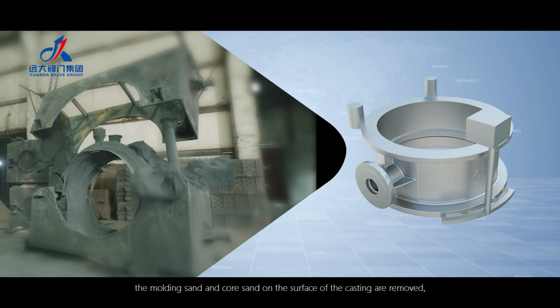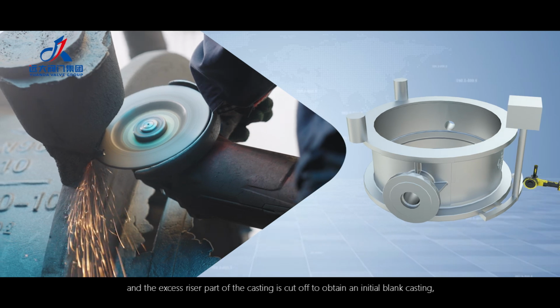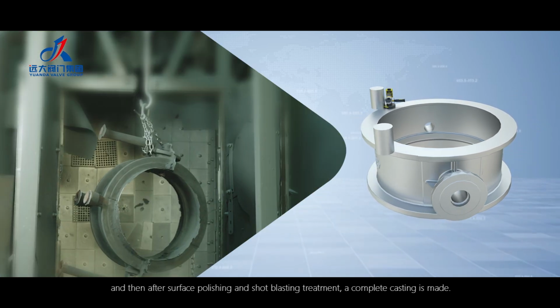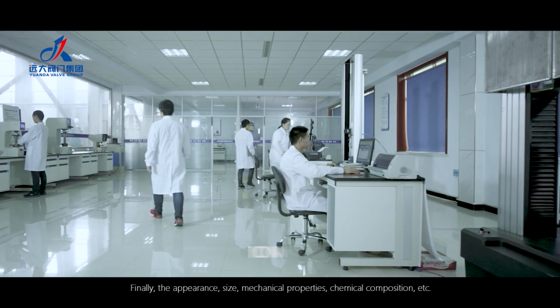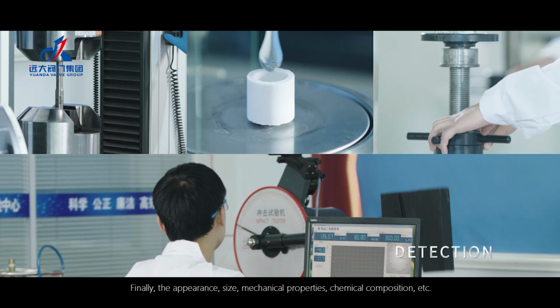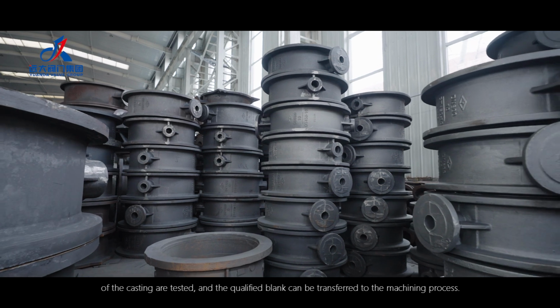The molding sand and core sand on the surface of the casting are removed, and the excess riser part of the casting is cut off to obtain an initial blank casting, and then after surface polishing and shot blasting treatment, a complete casting is made. Finally, the appearance, size, mechanical properties, chemical composition, etc. of the casting are tested, and the qualified blank can be transferred to the machining process.